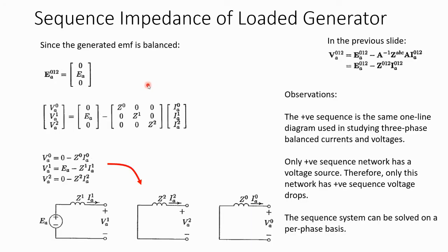So we are going to analyze the three-phase connected balanced generator further, and because they are balanced, we can say that the zero sequence and the negative sequence components of the generator are zero. In fact, this is a very important property that we normally ignore in the analysis of the balanced system, as well as in all the circuit analysis that you have learned.